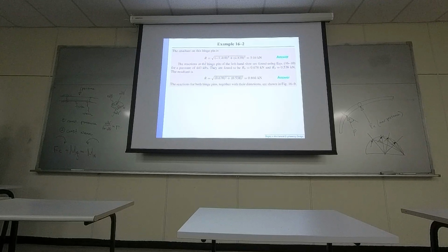So you will realize how much reaction forces are being applied to the joint, to the pins. And for the reaction force on the right, because there is more torque, it implies there will be greater reaction forces. So you can see for the right-hand side brake, the force is larger, and for the left-hand side is smaller.